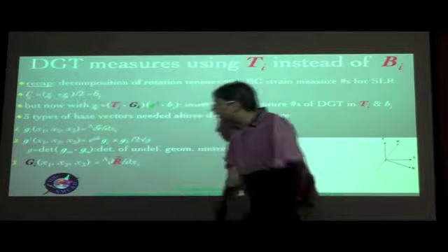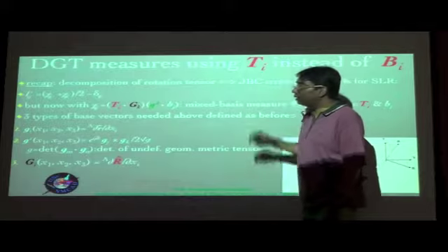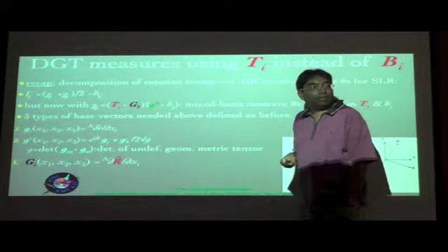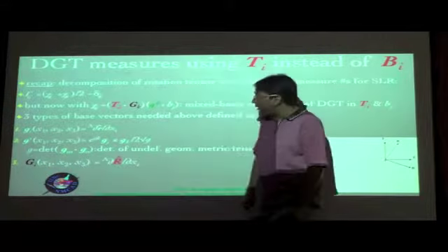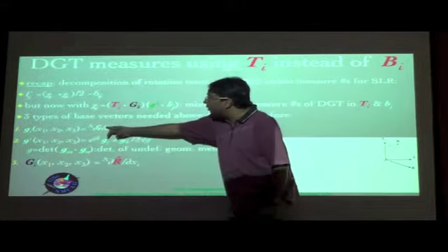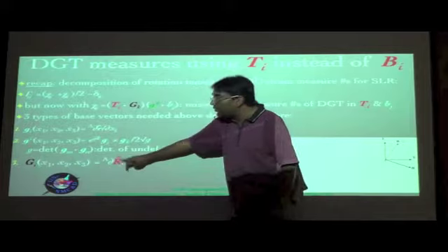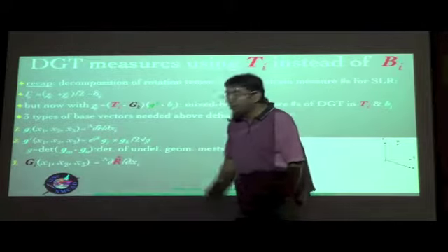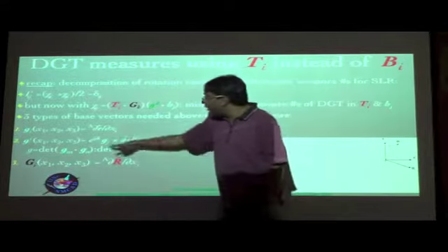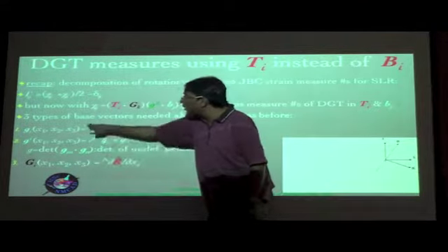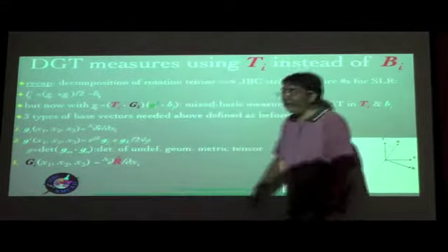Then basically your Gi, that is the covariant basis vectors for the deformed configuration, that is the uppercase Gi, are determined just similar to this. Instead of the small r hat, you have the big R hat. And once again, you take the differentiation with respect to the 3 cross-sectional coordinates. In both cases, the differentiations are with respect to the frame A.